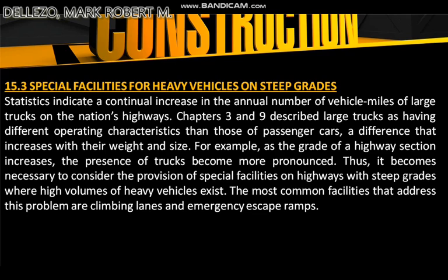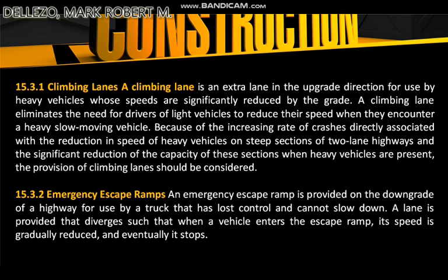as the grade of the highway section increases, the presence of trucks becomes more pronounced. Thus, it becomes necessary to consider the provision of special facilities on highways with steep grades where high volumes of heavy vehicles exist. The most common facilities that address these problems are climbing lanes and emergency escape ramps.